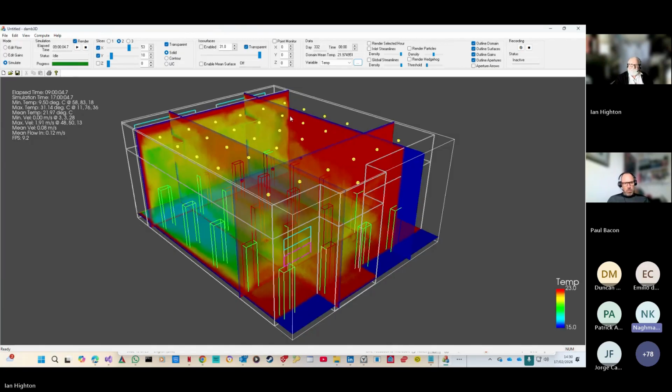Yep. For window openings, like mass flow rates and your surface temperatures, indoor temperatures, stuff like this. So it's directly linking and coupling the building thermal model now with dynamic hourly CFD, right? In a matter of minutes, which is the headline, basically, of what we're trying to communicate.